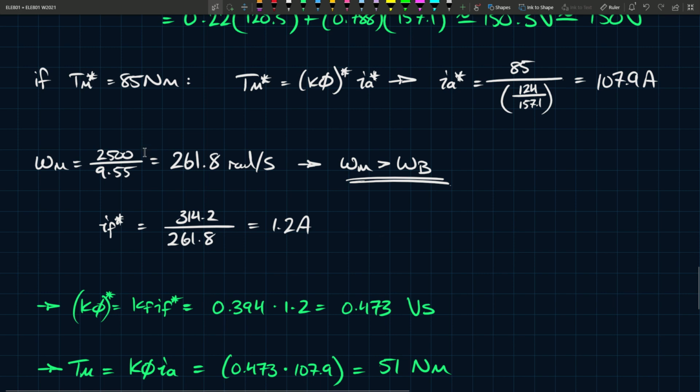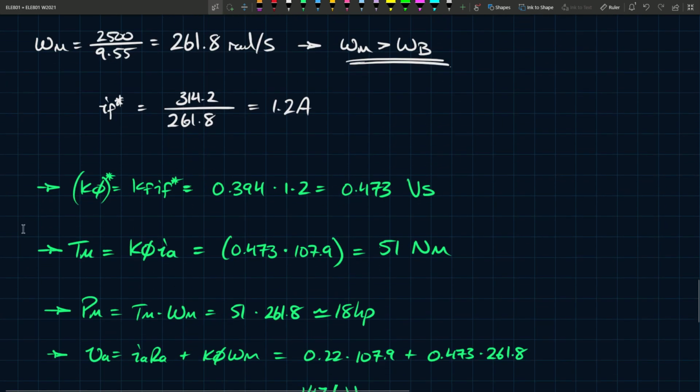And we found that in order to maintain this speed, you would have a reduced torque, since K phi is directly related to speed control but also impacts the torque. So the two are not independent, although we like to use them to control two different variables.